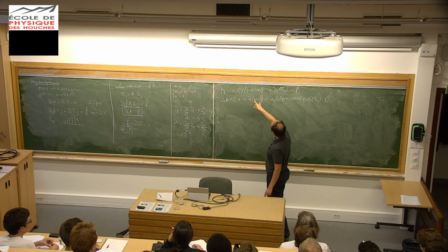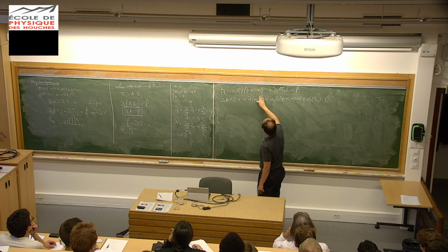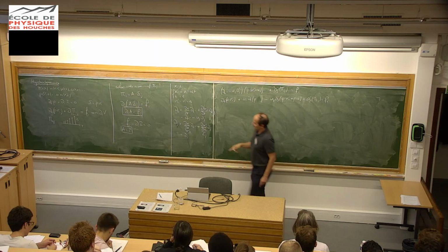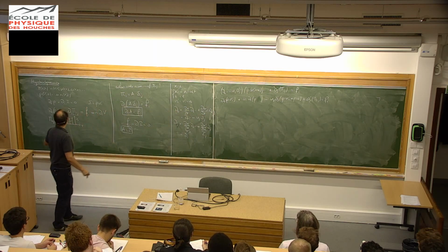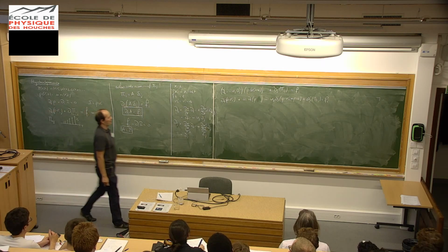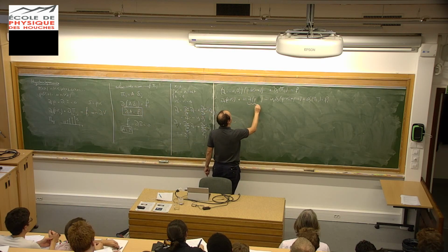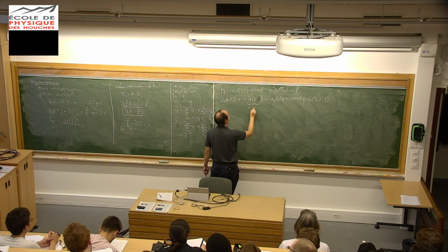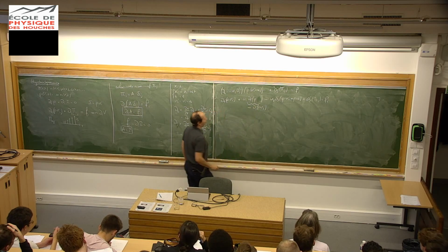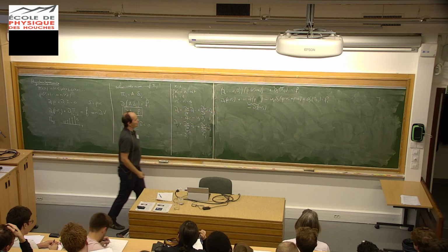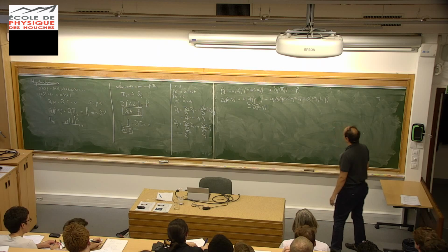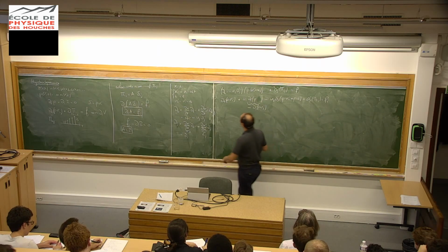What's it again? The second term you're writing. Oh yes, sorry, you're right. Because actually I was going to use the conservation of mass, where indeed there is no such thing. So using the conservation of mass, you can replace the derivative with respect to time of rho by a gradient, which is just minus ∂j of rho v'j, because here I'm working in the new frame. And so you see that all the terms which are not this one are in the form of a divergence. And so actually I can gather all these terms under this form.